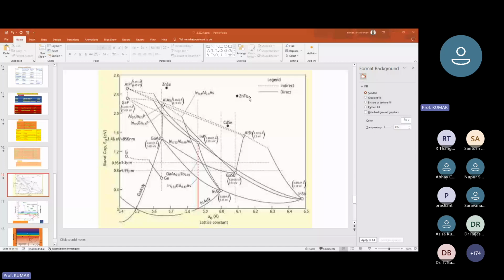And then as you go here, you see this area, the red spectrum is covered. So this band gap energy is EG4, which is very small compared to the first layer. So this first layer will absorb the high intense solar radiation. The second layer will absorb lesser intense radiations, and correspondingly weaker intense like infrared radiation is absorbed here.